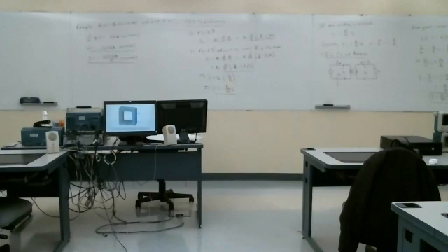If I'd chosen V2 like this, but the dot here was actually at the bottom, again, I'd have to use the minus sign. I get the plus sign when I have both pluses here at the dot. Now, if both dots were reversed, it would still be a plus relationship. If I had the dots at both assumed negative terminals, okay. But if I have one dot at a plus and one dot at a minus, then I need the minus